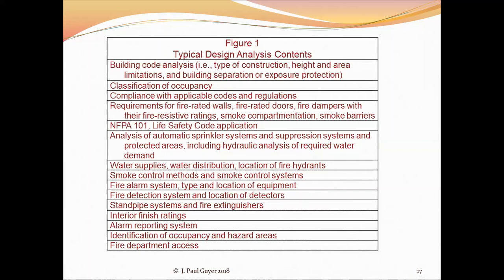The NFPA 101, the life safety code, there's a lot of kind of overlap here with the typical fire codes, but in essence, the life safety code, NFPA 101, is directed at the occupants of the building and making them aware that a fire is broken out and getting them out of the building expeditiously.